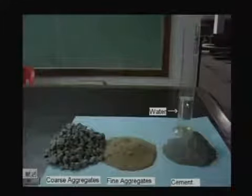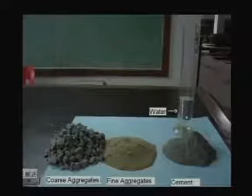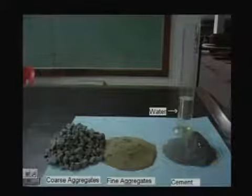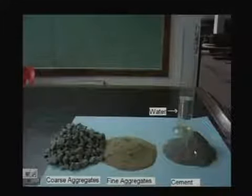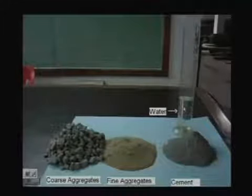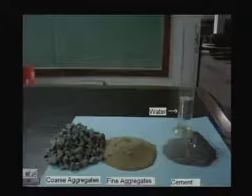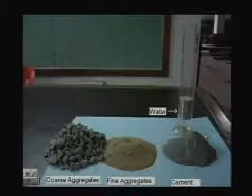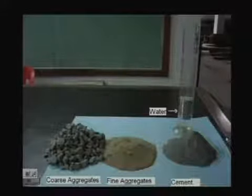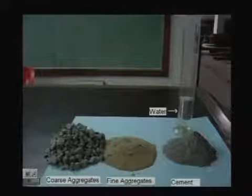And we also have to measure the water, through the water cement ratio. For a particular case, if we have 1 kg of cement, then we require 400 milliliters of water, considering a water cement ratio of 0.4. Generally it comes in the range of 0.4 to 0.5, depending on the target strength. So: coarse aggregates, fine aggregates, cement and water.